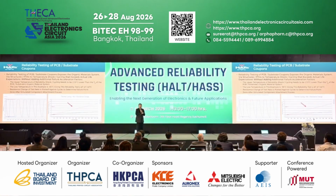So after the assembly simulation, we will start typical reliability testing. During the typical thermal shock or thermal cycling, we will let the coupons or PCB be exposed to hot and cold temperature cycling, and also monitor the coupon resistance change. With this coupon resistance change, we can easily determine if the structures are already showing some failures.